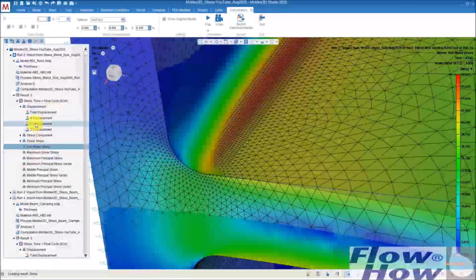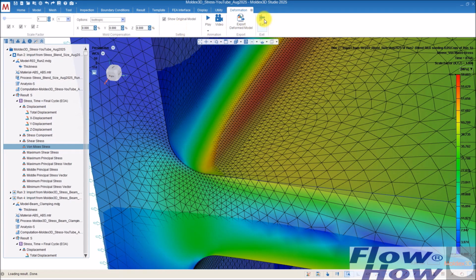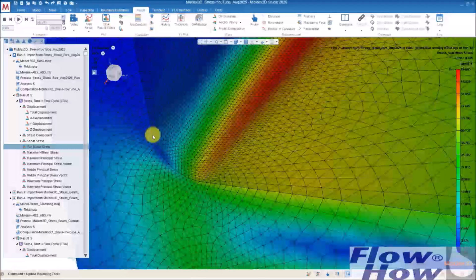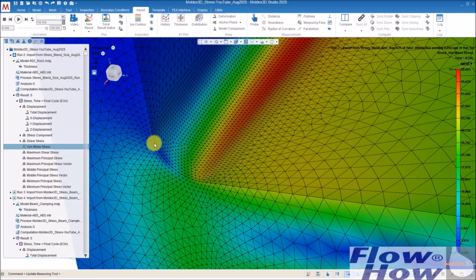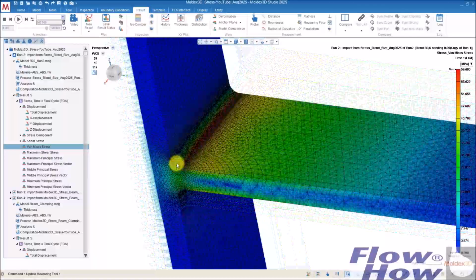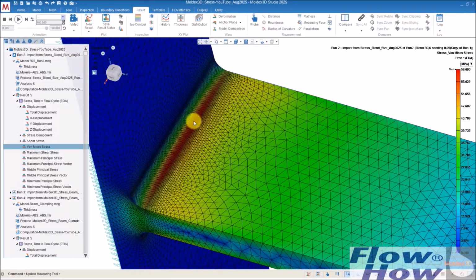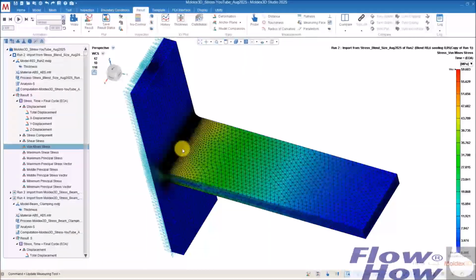I'll just go out of the scaling. This, you can see it. From this point to this point, minimum 8, but better 12, 16, like this, to have converged results of the stress.